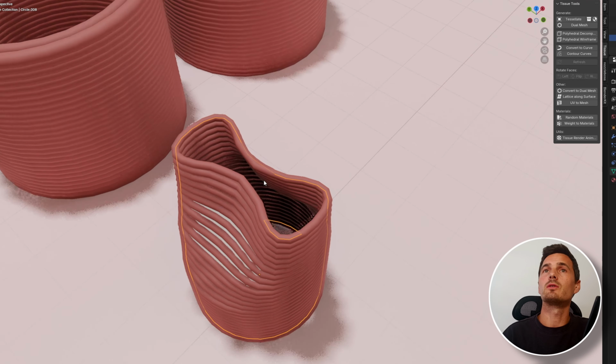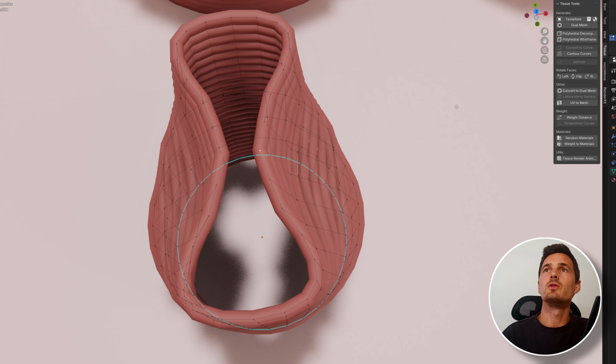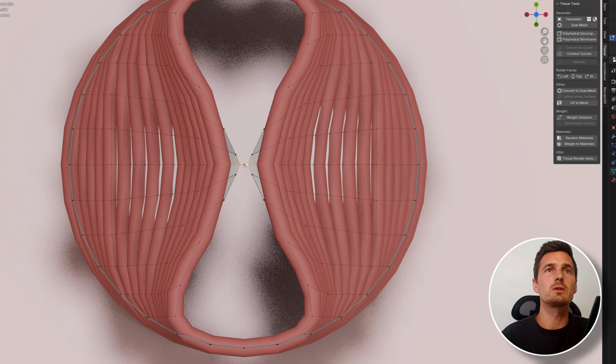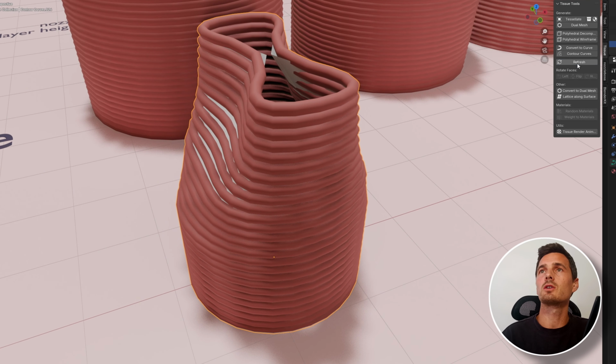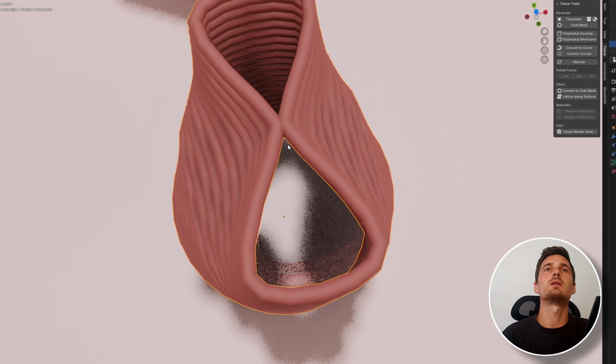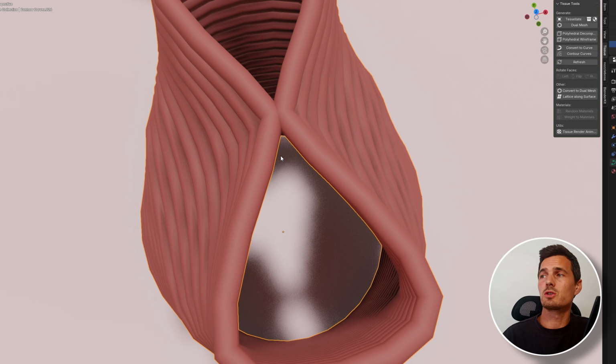But if you want to introduce some extra strength, you can make sure that these surfaces will barely touch each other. That will look like this. This is a little bit too much. So now it's overlapping, and if contours start to overlap, it will create defects because you have extra material.